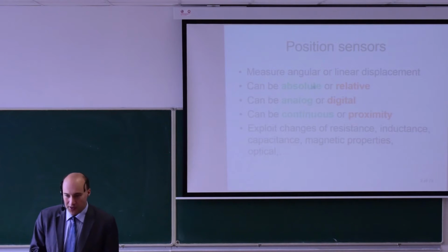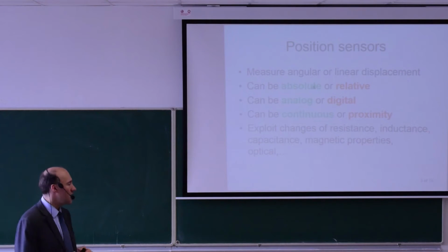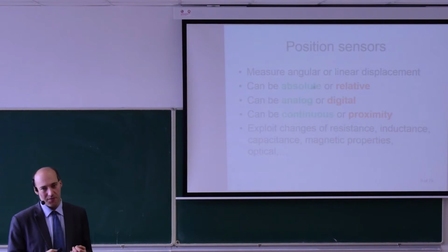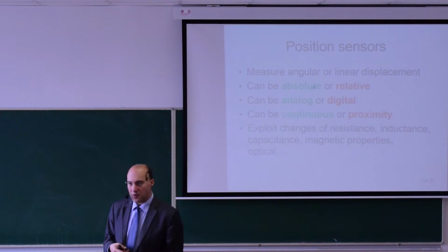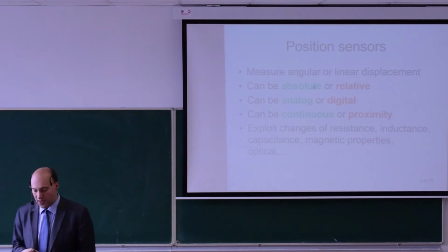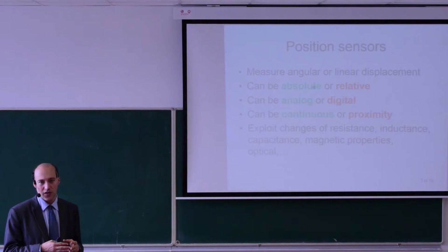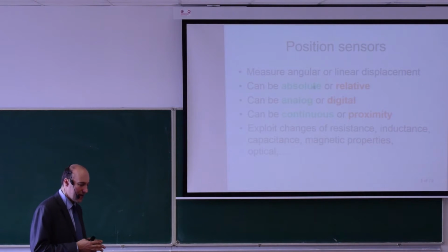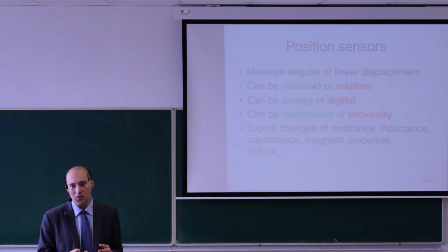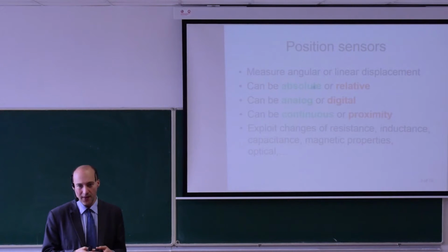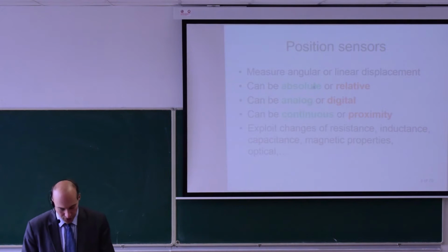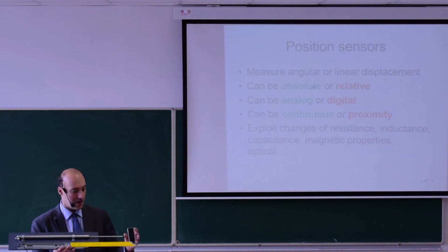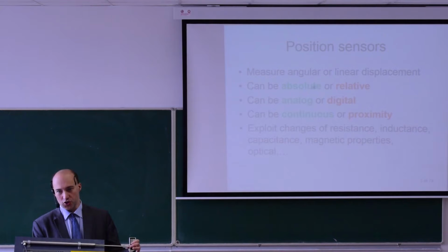The third criteria for position sensors may be the principle of the sensor: whether it's an analog sensor or a digital sensor. The sensors that we will be discussing today are all analog sensors. So they are able, in theory, to give you an infinite resolution.